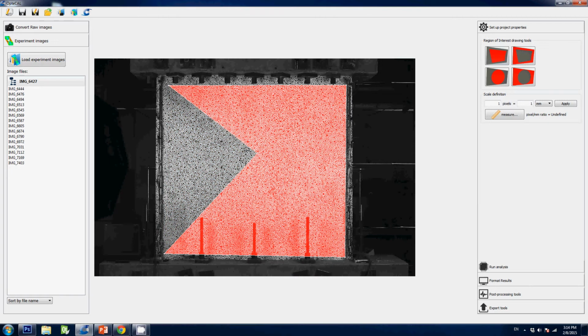Okay, when I'm done, I can either double click if I want to keep this last point here, or I can hit escape if I want to get rid of it. If by accident I keep it, so for instance I double click here, now I have this point that I don't want here. I can move it, but I can also right click on it and hit the delete point button here, and here we go, I got rid of it. You saw that you can also delete the whole shape if you want, but we're not going to do that here.